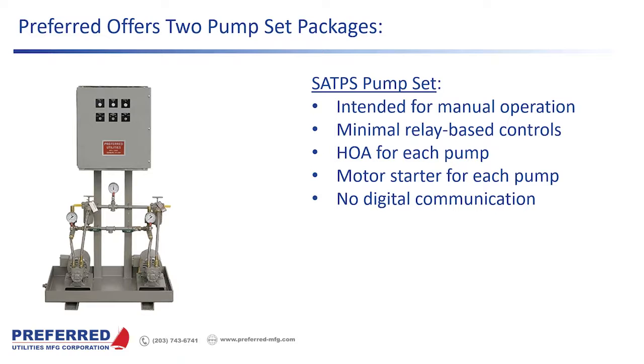So Preferred offers 2 different types of pump set packages. We have an SATPS. This is a semi-automatic transfer pump set that's intended for manual operation. It has very minimal relay-based controls. About the only real control function it does is it will automatically switch over lead pumps each time there's a call for operation. You get a hand-off-auto selector switch for each of the pumps. You get a motor starter for each pump. And there's no digital communications at all. It's all old-fashioned relay type controls.